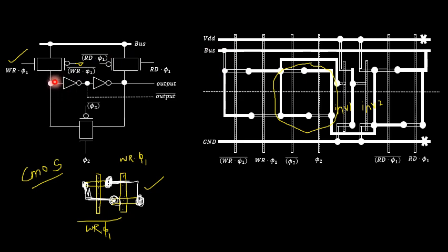Another one should get connected with phi 2 and phi 2 complement in parallel. So phi 2 and phi 2 complement in parallel, another end should get connected with that particular connection. So this is that connection. Understood? Then I am having an inverter 1 over next. So this is the inverter 1. So here it is CMOS design.